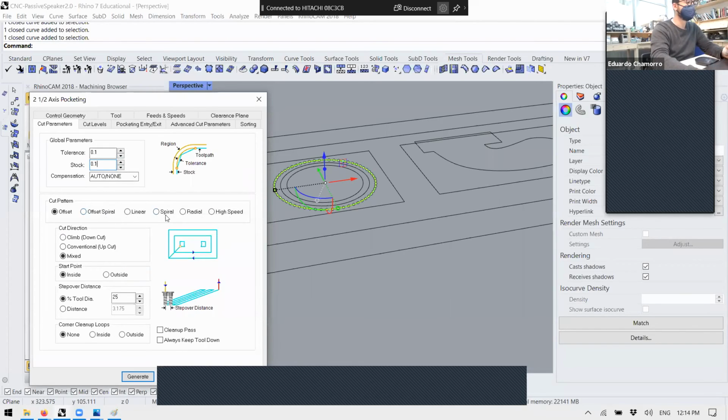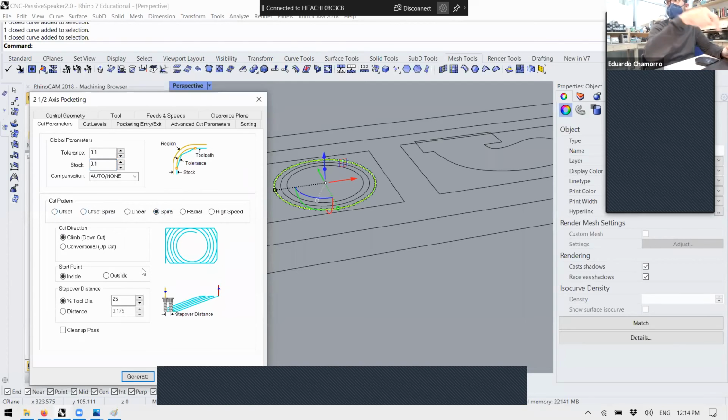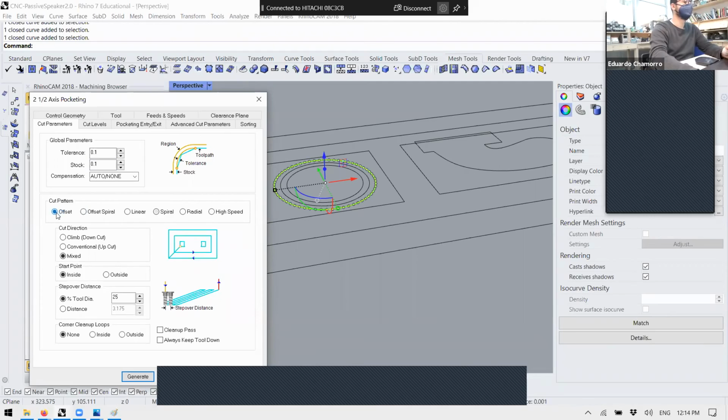It's a circle, so let's go for a spiral cut. It's going to be smooth. This is about transitions. If you make a circle and then you make a movement to make the offset and then not a circle, you will make a not smooth movement. With a circle, it's super easy to make a smooth movement just by using a spiral. You will be really constant on X, Y, and Z speeds.